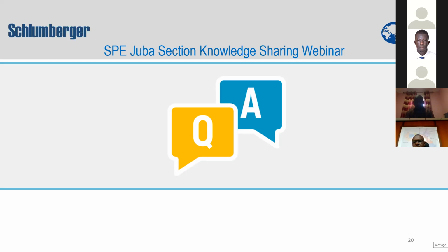And in most of the cases, the ESP is even healthy. So there is no need for you to pull the ESP. You just stop the ESP and then you do it. Most operators don't have an option other than to just wait until the ESP fails. Then at that time they will say, okay, when we are pulling the ESP, before we run the new ESP, you should mobilize Wireline to come and do the logging for me.